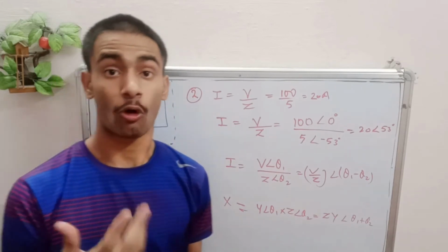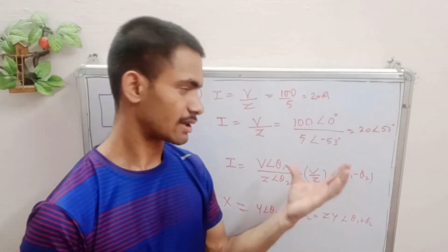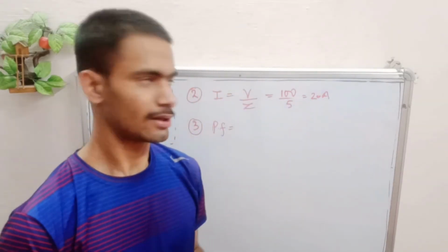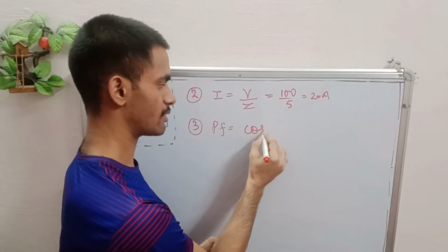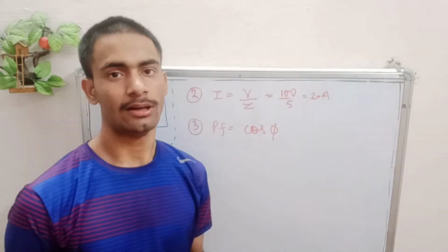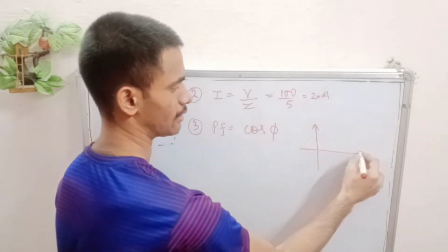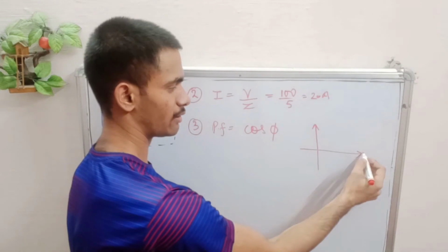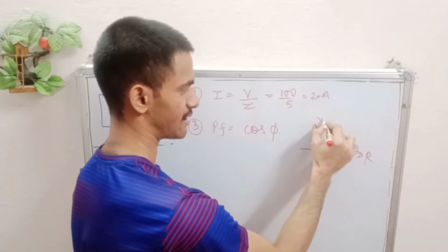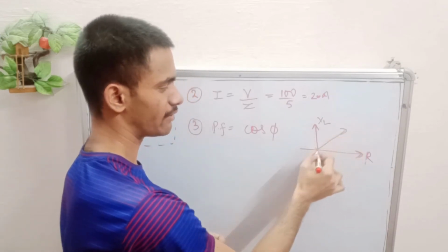This is just a complex form representation of some quantity, and it's a graphical way of showing it. Now what about power factor? Power factor is equal to cos of psi, or theta, and that angle is between voltage and current. But roughly, for easy calculation, you can take whatever the resultant of X R and XL XC is, making some angle with this one.